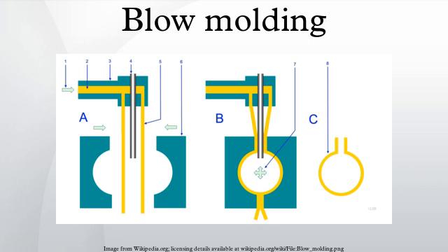The preform mold opens and the core rod is rotated and clamped into the hollow, chilled blow mold. The end of the core rod opens and allows compressed air into the preform, which inflates it to the finished article shape. After a cooling period, the blow mold opens and the core rod is rotated to the ejection position. The finished article is stripped off the core rod and as an option can be leak tested prior to packing.